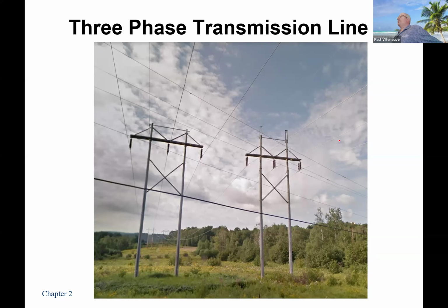And that just shows you pretty simple construction. In Maine, we go with H-frame construction. It's cheap. Plus, we can go pretty straight. You can look, it's hard to tell, but these lines are almost exactly perfectly lined up with each other. That way you don't need to worry about guy wires. It's once you start doing twists and turns that you've got to start getting more creative with guying.